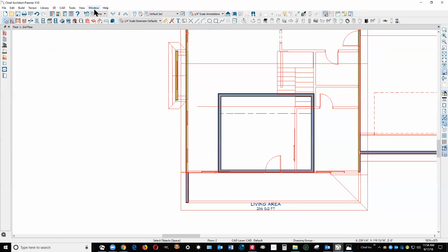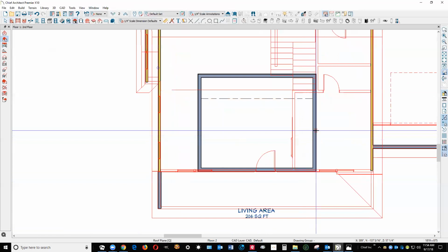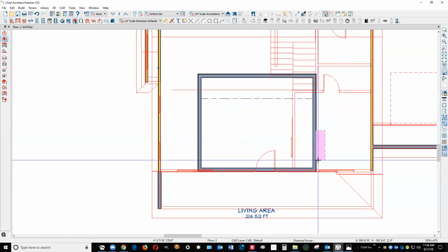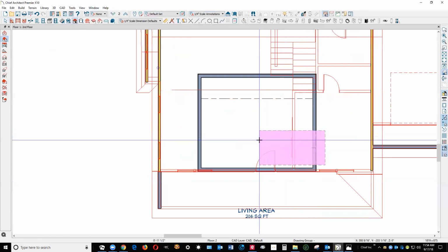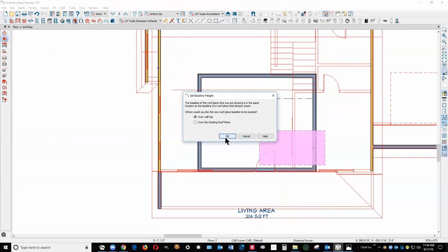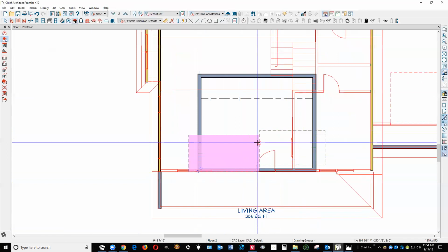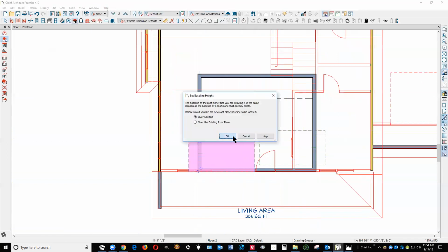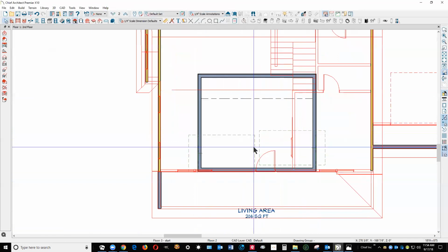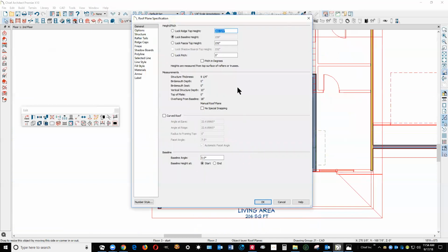And so what I'm going to do is draw a roof plane. And I'm going to have to change the height on these because they're going to come in too high. Opposing roof planes here. And remember that I haven't changed the default pitch from 5, so I'm going to have to manually change these from 5 to 12-12.